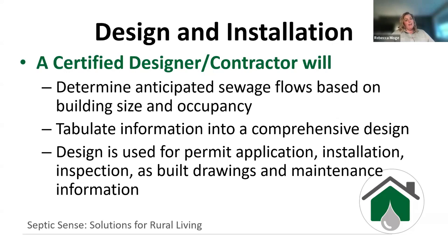So again, starting with the soil, once we know what the soil is, then we base our design off of the soil. If we don't have a good understanding of soil and we're not conducting that site evaluation appropriately, we may be installing a system much bigger than we need, or worse, installing a system that's smaller than we need and possibly end up looking at a system failure.